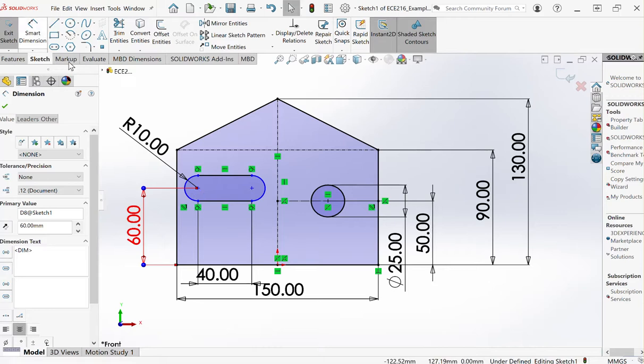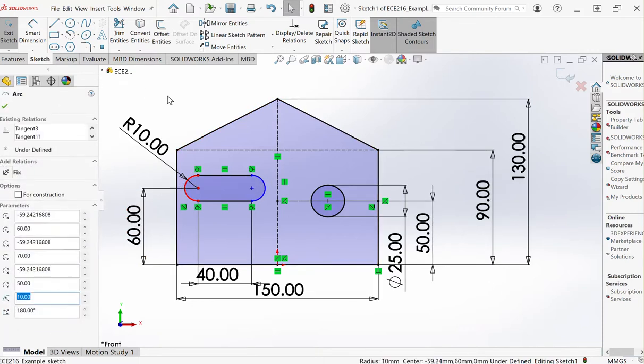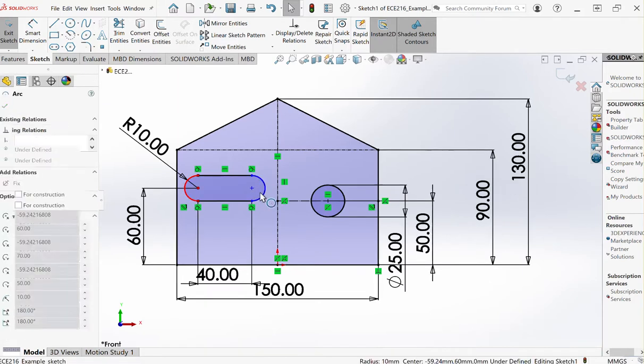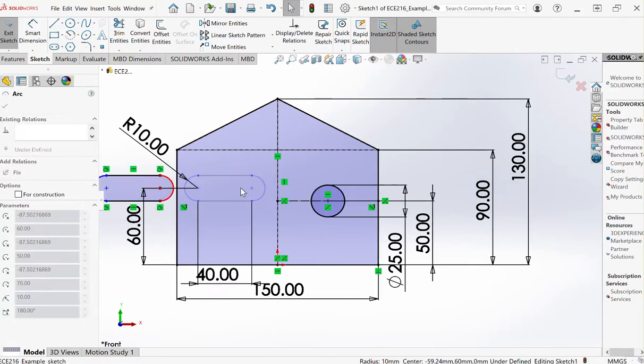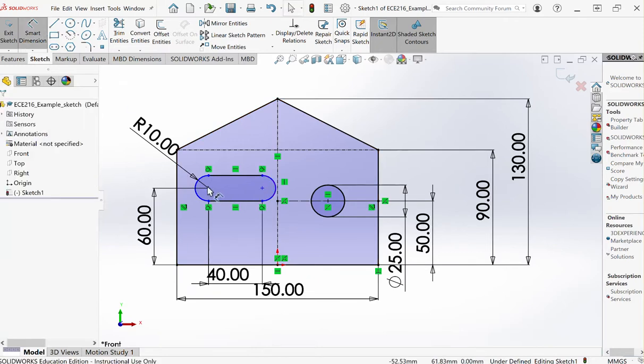And we miss one more thing. So if you still have something in blue in your sketch and you don't know what it is, just take it and see how you can move it. Oh, I cannot move it. Why can't I move it? Because I should be able to move it to the right and to the left. Oh, here we go. You see, the only thing that is missing is the fact that I am going right or left. I'm sorry, there's a gardener outside. I'll finish this video quickly.